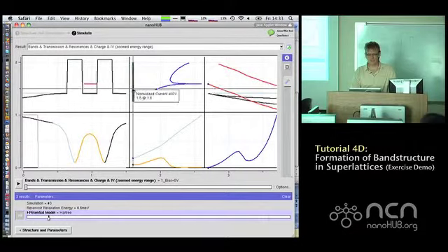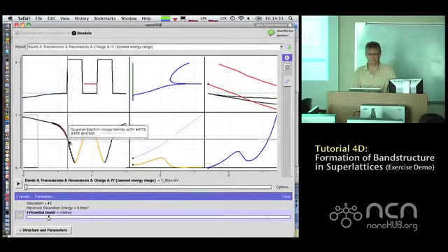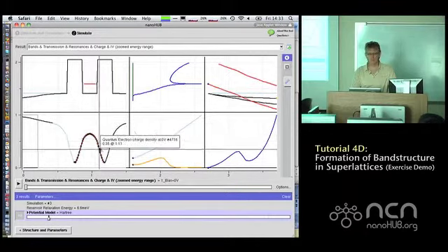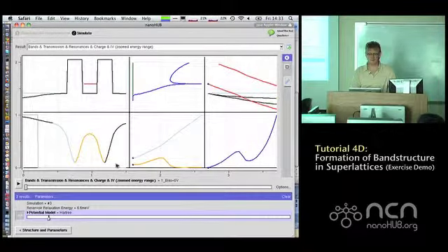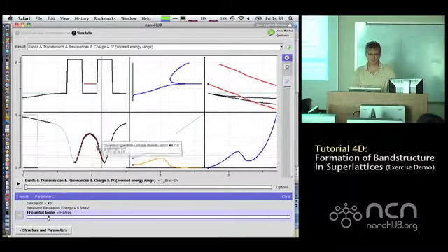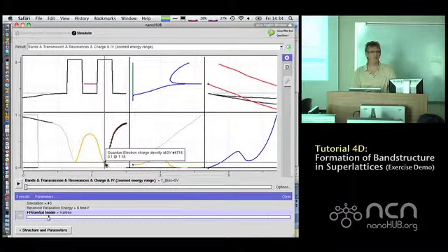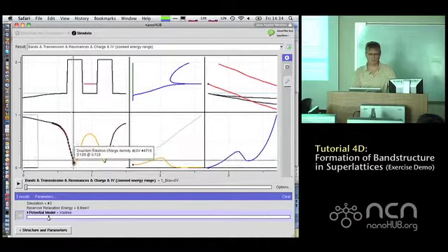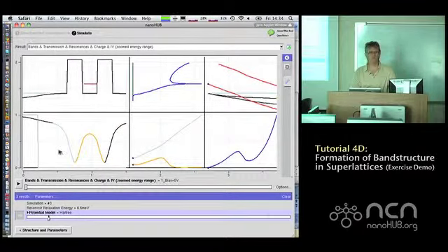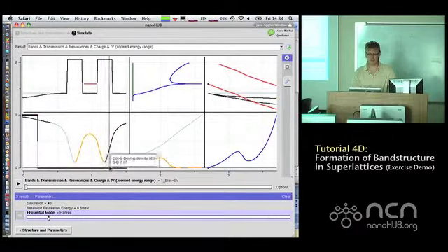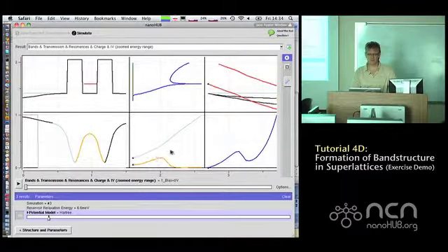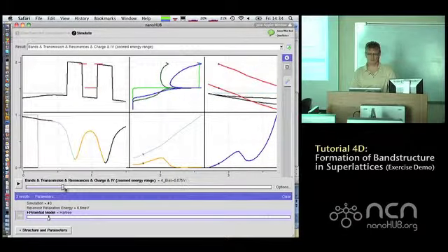So here's now charge like this. It's smooth. We built this GUI, and this orange here is what we would consider in the well, and what we have in the emitter is in the light blue. We can integrate over that region, and you can actually see that charge is piling up in the well, and then it's emptying out. As you ramp up the voltage, current starts to flow.